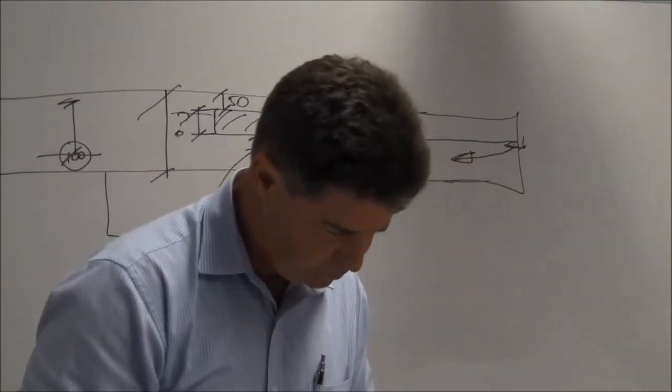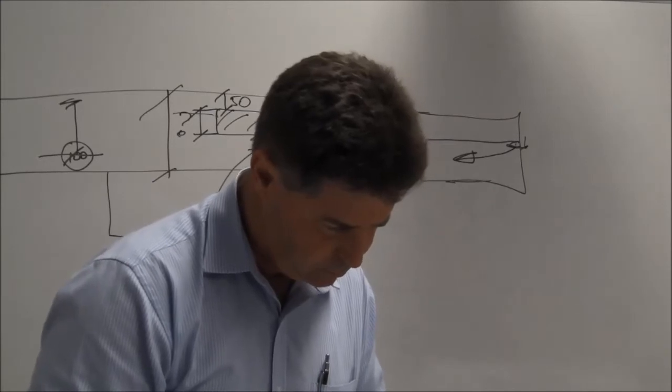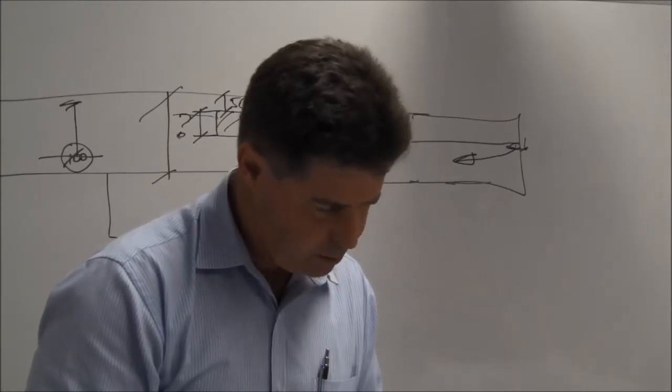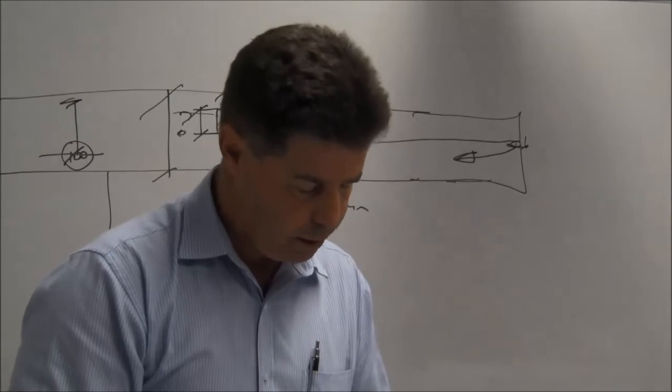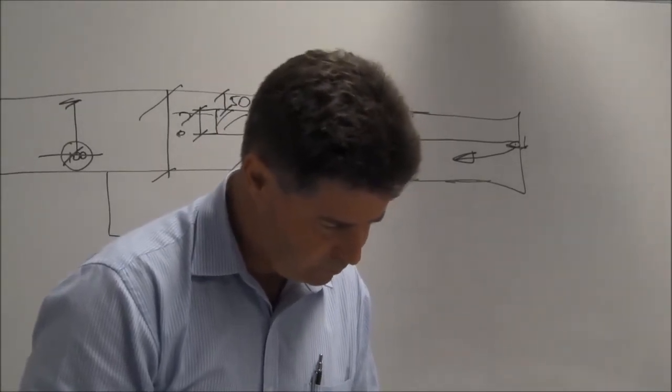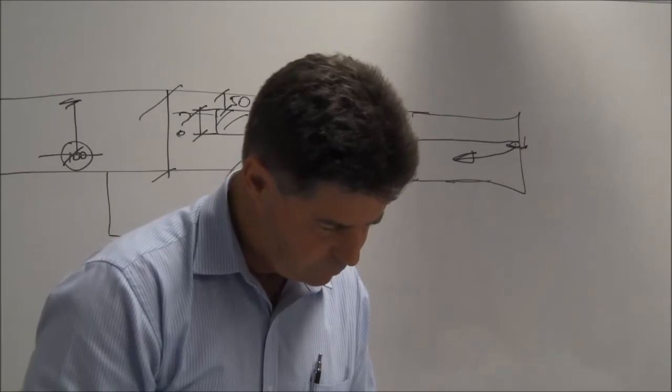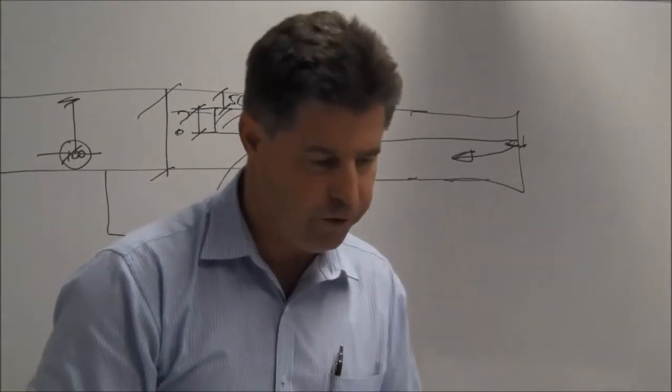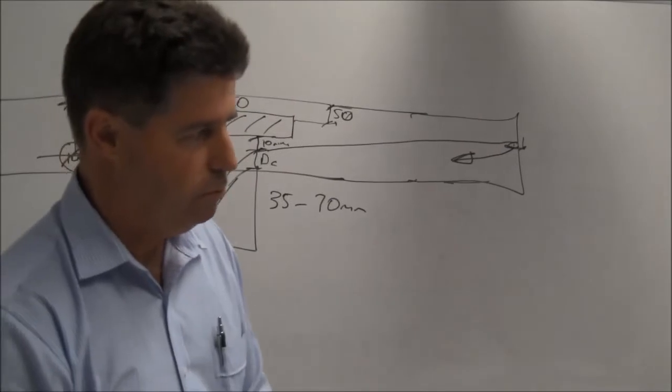We've got the 30 mil against the normal. The 30 mil is our 35, is that? That's correct, that's critical depth, plus the 10. And then it's the next 50 that I don't understand. The 50 is the freeboard over the top. We must have a freeboard.